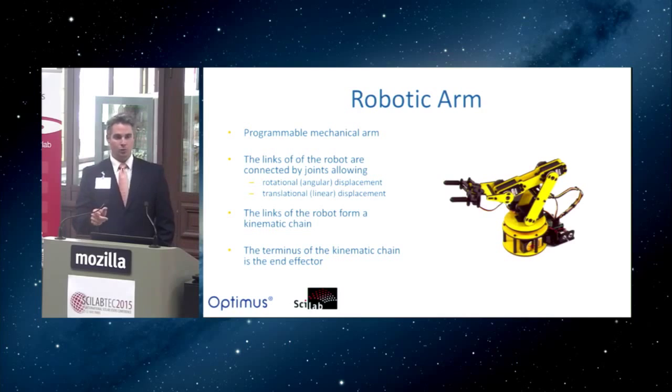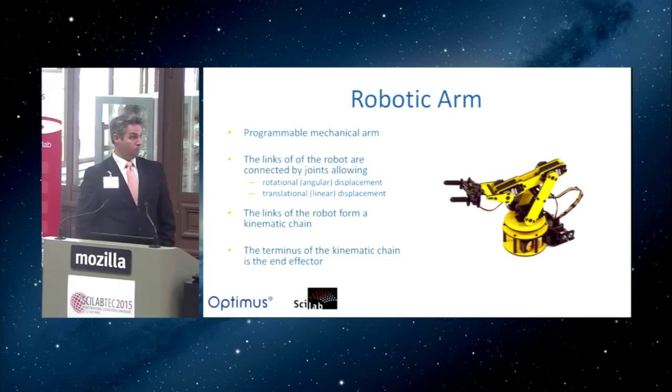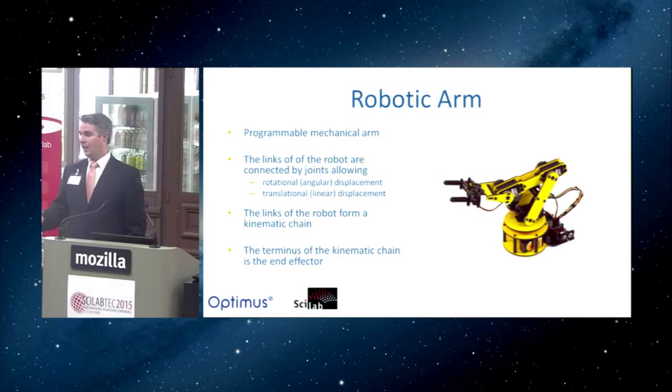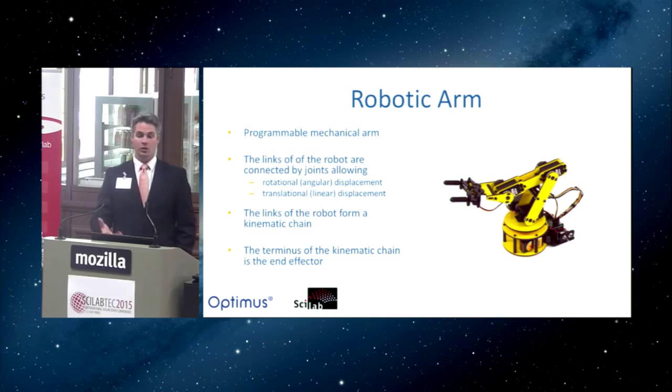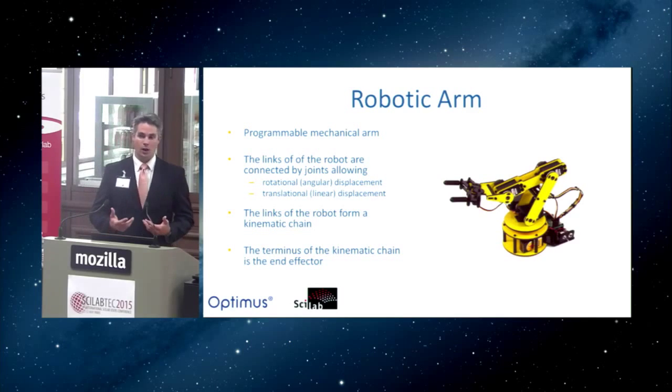The PID loops that control these are extremely important. Basically, the control system for this particular robot has a PID loop for each individual servo motor. Those are basically tuned at production time. There are situations where you need to tune these PID loops in real time, and so you're always updating and you're always tuning these PID loops, and that actually opens up a wide variety of applications for optimization.